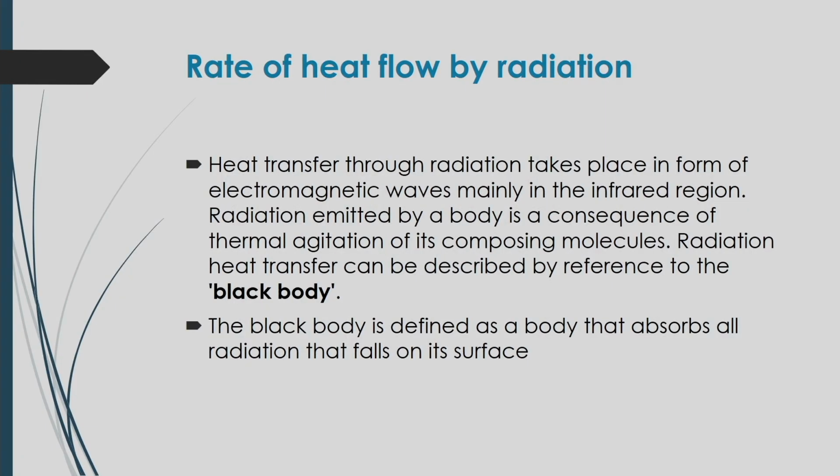Now, in this case the heat transfer through radiation takes place in the form of electromagnetic waves, mainly in the infrared region, and radiation emitted by a body is actually a result of thermal agitation of its composing molecules, and radiation heat transfer can be described by reference to the black body. The black body is basically defined as a body that absorbs all radiation that falls on the surface. If the body is absorbing all the radiation, then the body will be regarded as a black body.